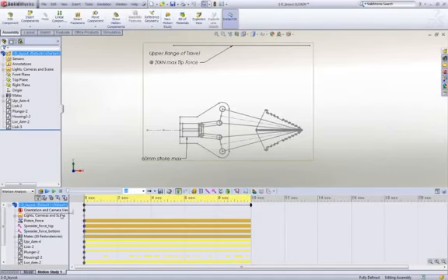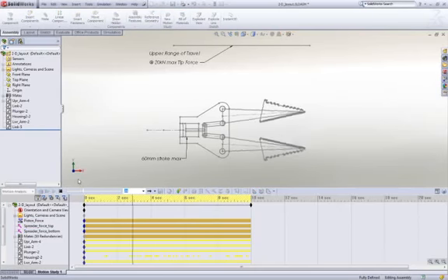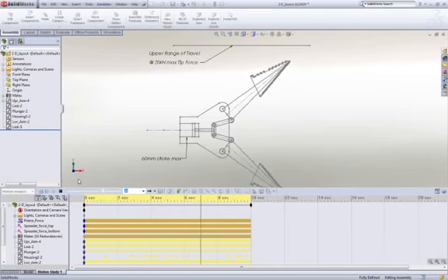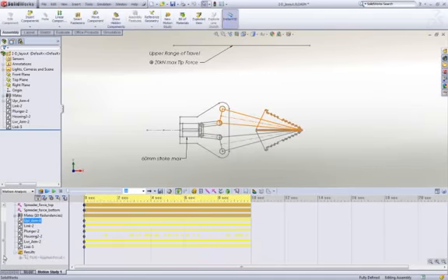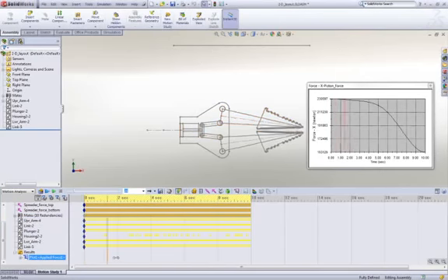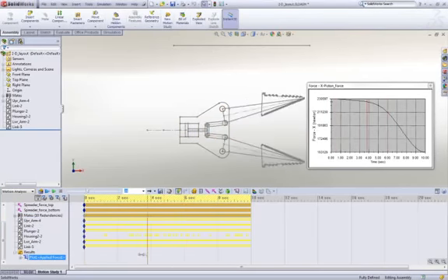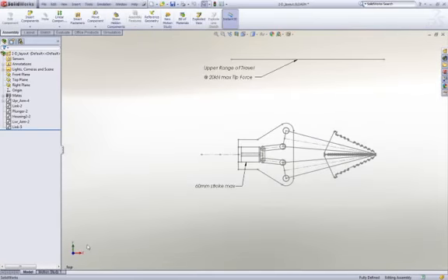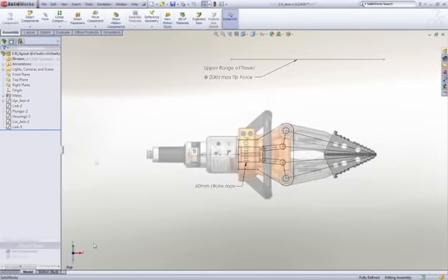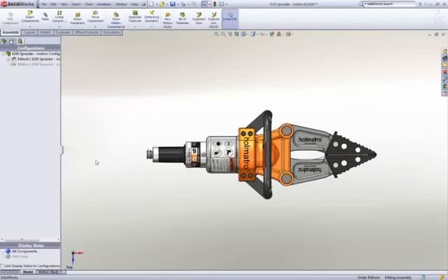We've seen how we can assemble our design in SOLIDWORKS, but how do we know it's going to function correctly? It's invaluable to be able to validate the spreader operation without the need to cut metal or build prototypes, like in the case of this sketch layout concept. With SOLIDWORKS Motion, we can easily test our design during the early stages of development to aid in sizing parts, bearings, motors, and actuators to ensure they meet our design goals. As we go through and refine our design, we can continue to use motion to validate the function.